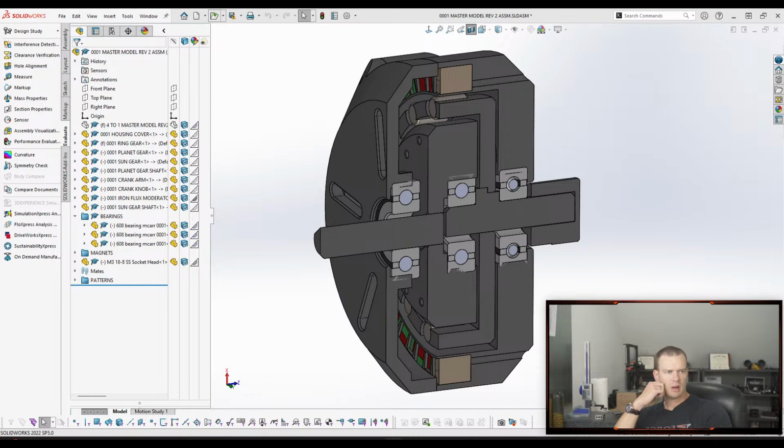Mm-hmm. I'm trying to think. So I know I've worked on larger projects before where we save out the skeleton sketch, that folder part, right? We save that out as a part to the vault, and then you can open that part, insert it into an assembly, and then model from there, right? And that folder part basically has all the information that you need to pick up your relationships to any exterior parts.